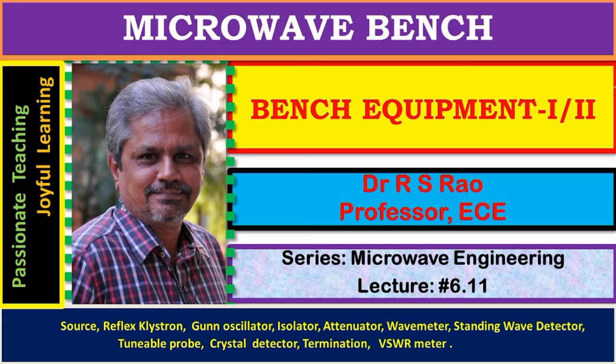The introduction and description of the bench setup, various devices, various meters that are part of the microwave bench, is given in two sessions. In the first session, mainly the focus is on frequencies and wavelengths that are associated with the microwave bench. Usually the bench is made to work over a certain frequency range with a certain frequency band. Depending upon the frequency range for which it is designed, the waveguide run in the bench has certain dimensions. We consider frequencies and dimensions of the waveguide run in the first session. Along with them, we also come to know about different components that are normally present in the microwave lab of an educational institution.